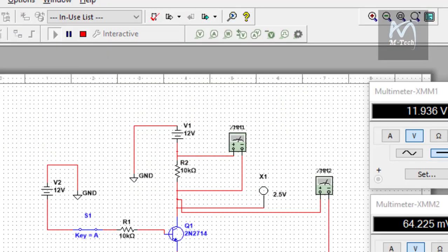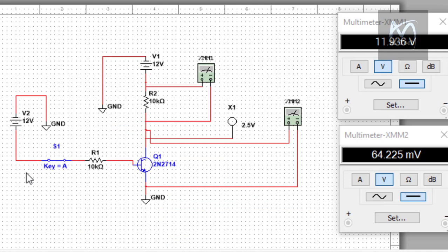So when we have a high input, that means we have 1 at the input, we will have 0 at the output. This is almost 0, and all the voltage will go through the transistor, just because we've opened the gate here by using this voltage.